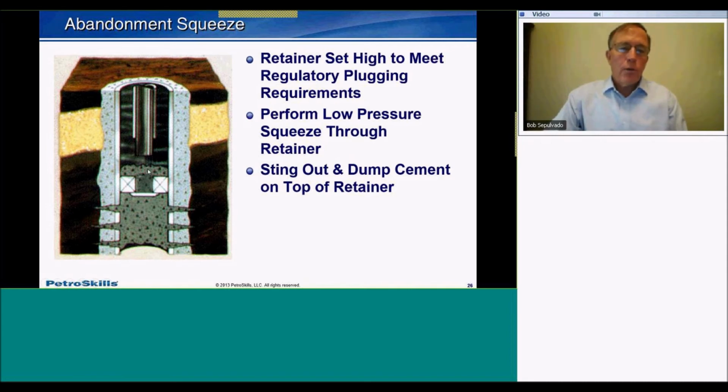We come off the retainer. The valve closes and we may, just for added insurance, dump some additional cement on top of the drillable tool and then come out of the hole. And that's how you abandon squeeze perforations, or you abandon perforations in a production interval.